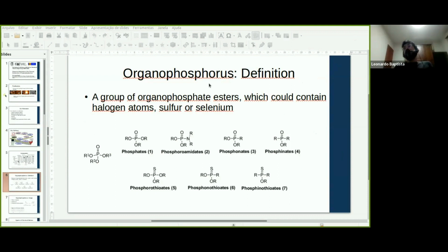And if we change the fuel from biogas to ethane, we see a better destruction of DIMP, DMMP, and sarin relative to biogas. So the fuel chosen for the incinerator can affect the destruction of all compounds.